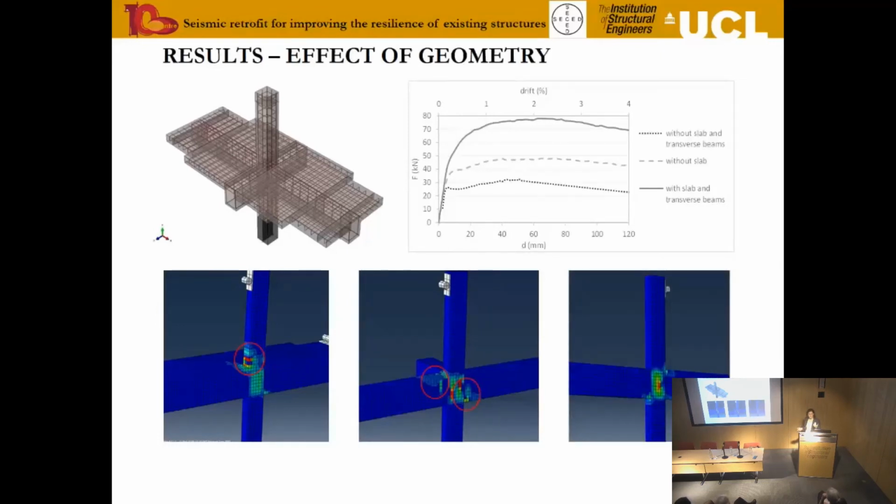If we remove the secondary beam, you actually get concentrated damage solely in the joint. Most experiments out there, most guidance is based on experiments that have this sort of configuration. So retrofits are looking to basically target that sort of damage, damage in the joints, whereas in reality the damage is happening in the columns. So we're dealing with two completely different strengthening targets here, if we assume what's in the codes and don't take into account what's there in practice.